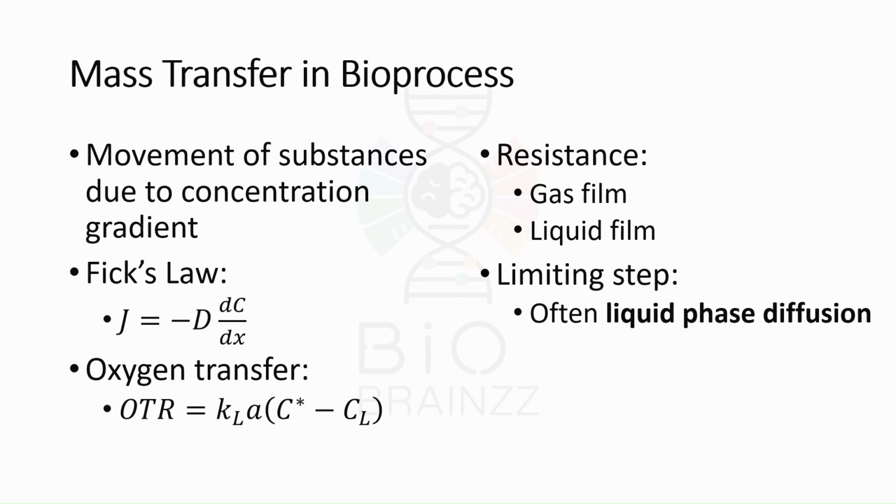Mass transfer is movement of substance from high concentration to low concentration. It follows Fick's law. In bioprocessing, oxygen transfer is very important. The liquid film usually offers more resistance, so it becomes the limiting step.